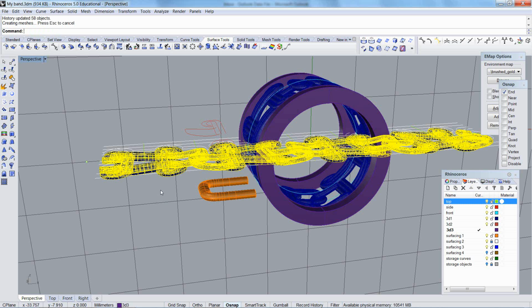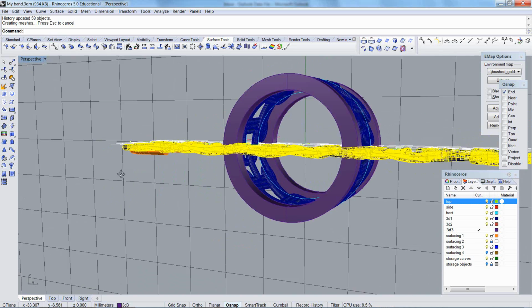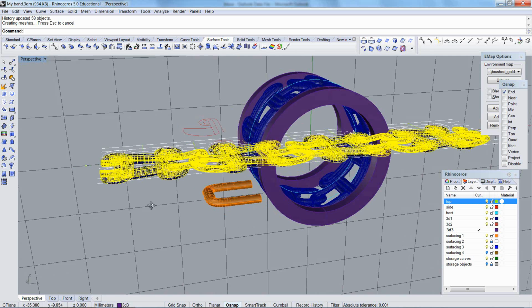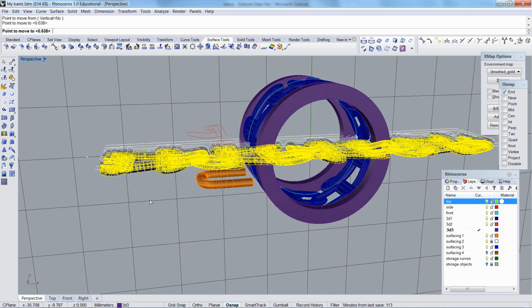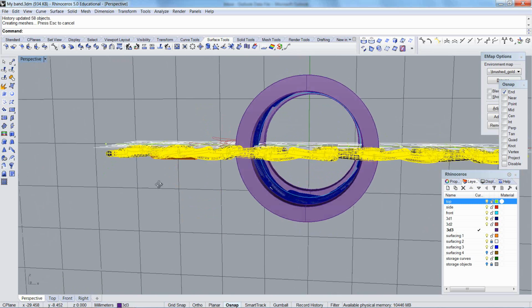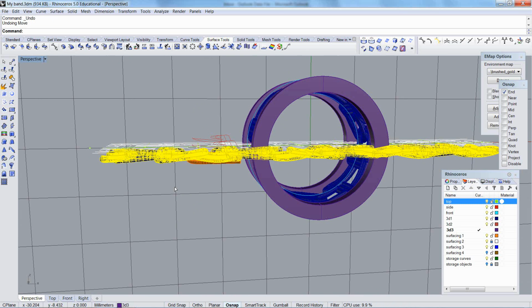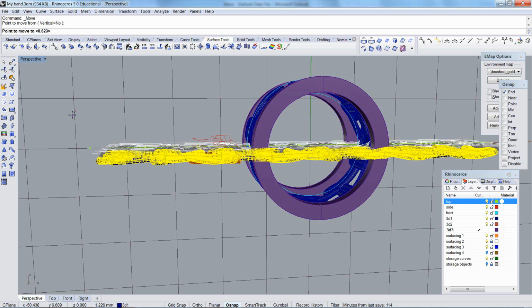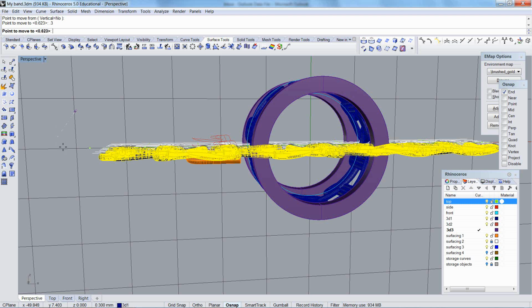Take a look. See how I like it on the inside. I'd like it to move down a little more. That's a little too much. Undo. M-enter. Remember, it always remembers the last distance on move. So I moved 0.6 last time. It was too much. I'll do 0.3 this time. Constrain it to 0.3. Hold Shift key to pull straight down.